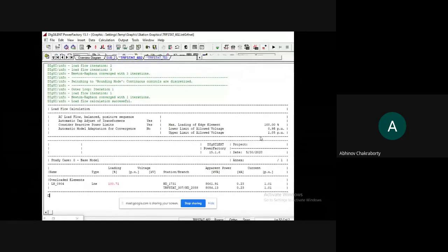That means you are giving a 5% tolerance to the system. So the lower limit of per unit comes to 0.95 and the upper limit goes to 1.05. Under standard conditions, you will be taking it to be 1 per unit. 1 PU will be the representation. That is, your actual and base quantities will be taken to be the same, and you will go for the manipulations. But you will obviously have a tolerance, and the tolerance in the system is 5%.